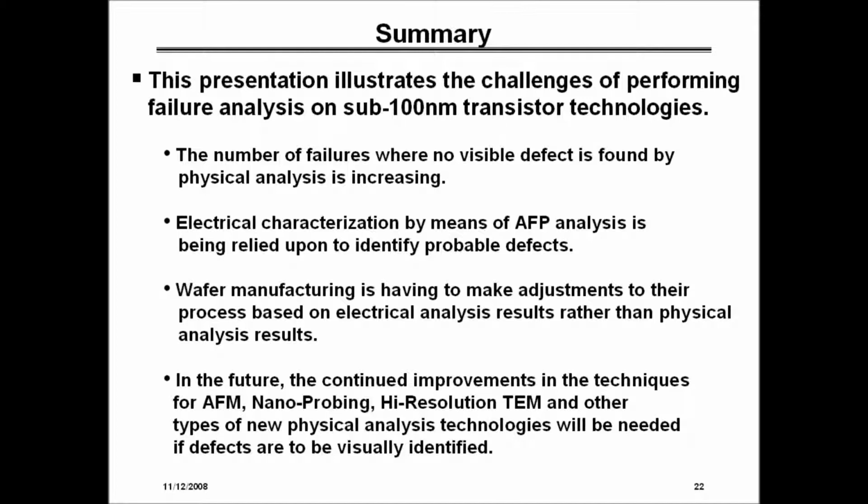At first we had difficulty with it. It's not easy when you first do it, but through practice and some techniques that we use now, we've gotten a lot better at it. We try to probe on the metal lines rather than the vias. The vias tend to deform when you push on them with the probe tips, when you delineate them so they stick up above the oxide. If you deprocess to the metallization layer, they're supported on the side with the oxide on each side, so they can take much more of a beating and hold up. So we found that works better.